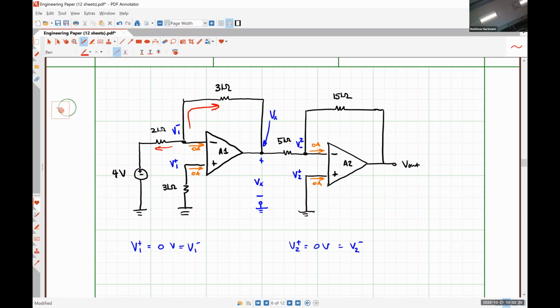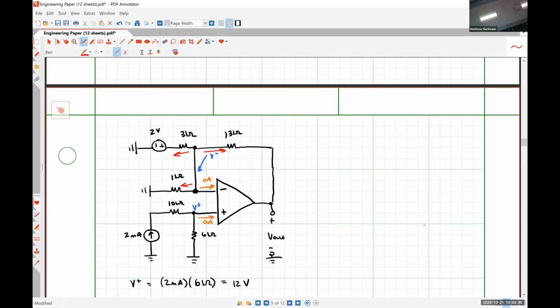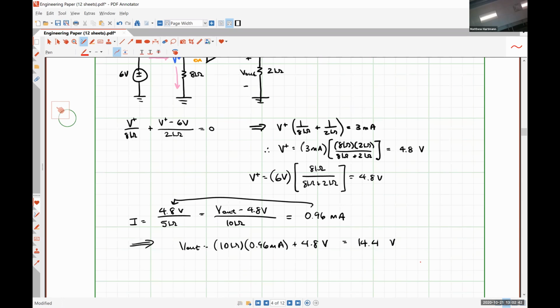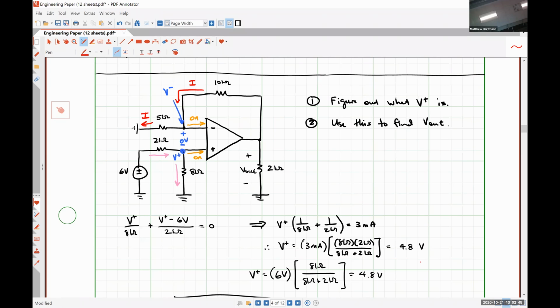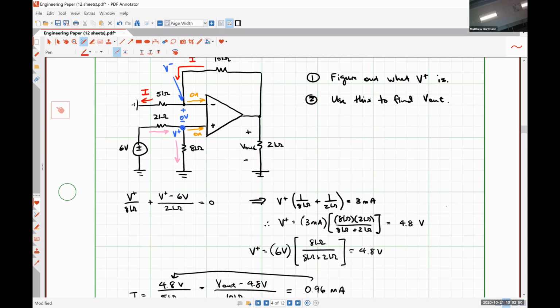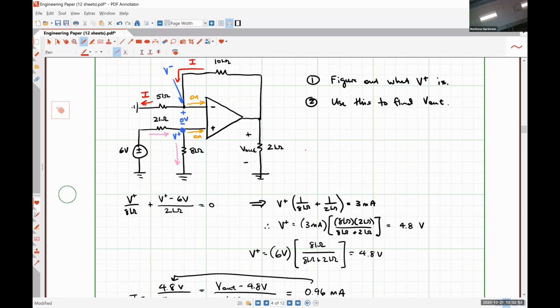That's one of the beautiful things about an op amp, is that the voltage present at the output pin of one op amp isn't really dependent on what you load that op amp with. So what I mean by that, if we look back at these previous examples, this guy has the output voltage over an open circuit terminal, whereas this guy had an output voltage over the 2 kilo ohm resistor, but we didn't in any way, shape, or form actually change the way we worked the problem out. And this first guy, that 2 kilo ohm resistor right here, never even showed up in a single one of our equations, right? So what we're loading the op amp with doesn't particularly matter.